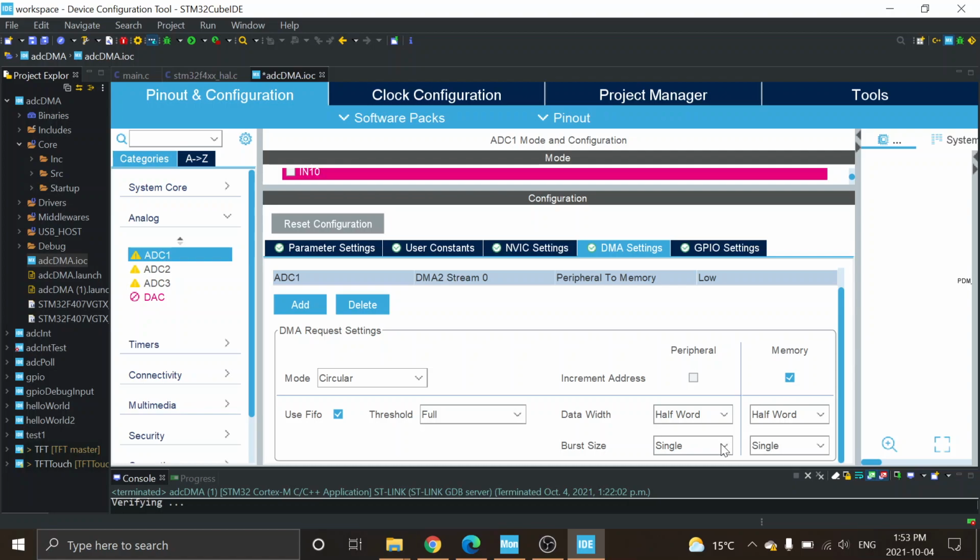One of the things about the libraries, if you use half word, is it will give you a little exclamation mark saying our library says it's 32-bit and you have 16-bit, so it's going to truncate it. It just gives you a little warning. So if I'm wasteful and want to just say, hey, let's just move 32 bits at a time.